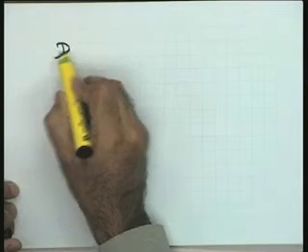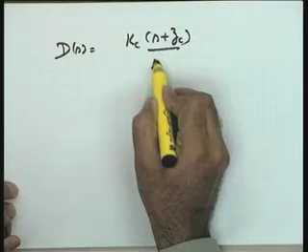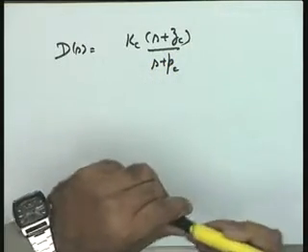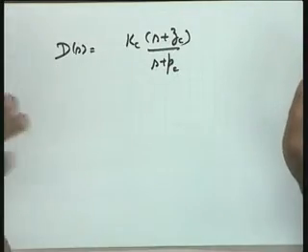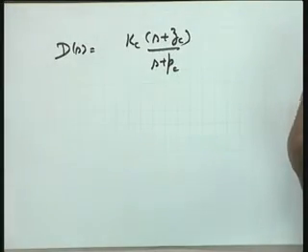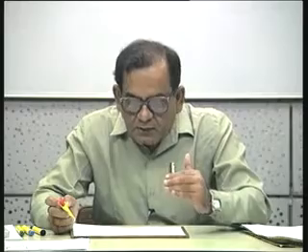I take this K as being replaced by D(s) equal to Kc (s plus zc) over (s plus pc). This is what I need. You see that the design procedure is really not a procedure which can be followed step by step. All of you for this particular problem will be giving a different design, but all the designs may be acceptable, and therefore what you have to concentrate on is the concept behind the design and not the exact procedure, and my effort will be to illustrate the concepts, and this example has been taken for that particular objective.